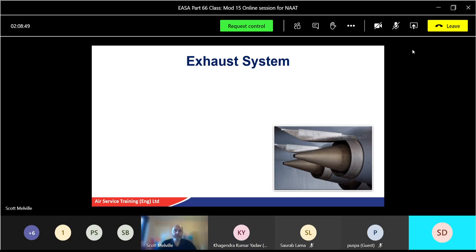What does NGV stand for? Nozzle guide vane. And what shape do they form? Is it convergent or divergent? Convergent duct. Convergent, yeah. You want to speed the gas out of the combustion chamber, so by making it convergent, velocity increases, pressure and temperature decrease. So you'll see a rapid decrease in the temperature and pressure, but certainly we've got the velocity. As the gas comes out of the NGVs, it hits the turbine, and we will lose a bit of pressure and energy, but then the next set of NGVs will speed that gas back up again to help the second stage.